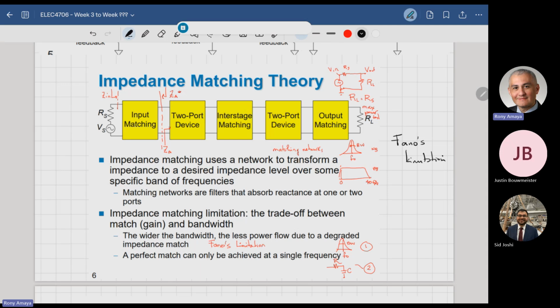That's exactly it. The purpose of it is to make sure that you have maximum power transfer, that all you can put in goes in and doesn't come back to you. Reflections are not good unless you purposely are trying to do that, and sometimes we do. But in general, we want to get as much into it as possible. When you have a discontinuity, meaning one impedance is different from another impedance, the moment that happens, that discontinuity will yield reflections. Those reflections are inevitable, but they can be controlled.